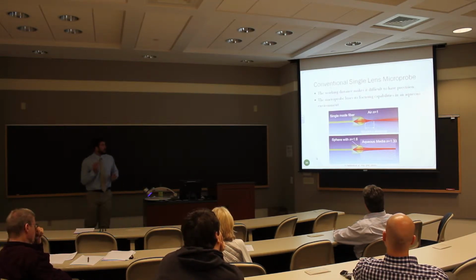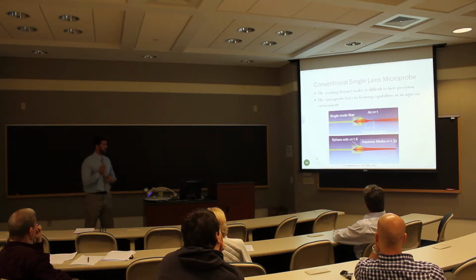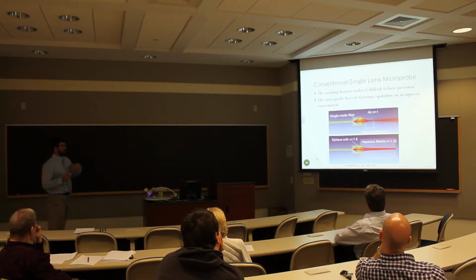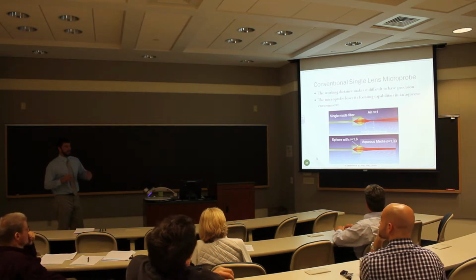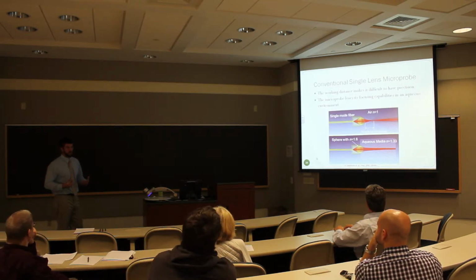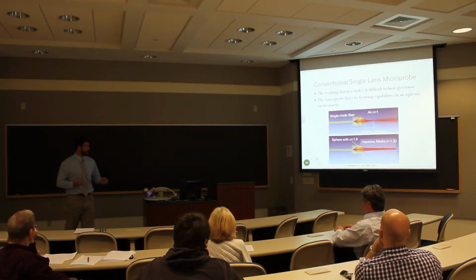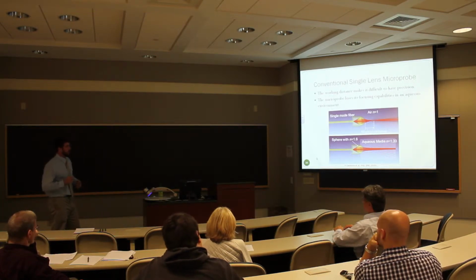So if we consider a conventional single lens microprobe of relatively low index, or 1.5 for example, and then a single mode fiber, the result of this is you're going to have a long working distance. And then also, because of this long working distance, when it's placed in an aqueous medium, it can't preserve its focusing effects. It's going to lose those focusing effects. Also, the wavelength chosen for this application, 3 micron, is not supported by single mode fibers.